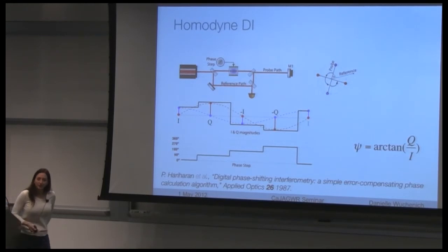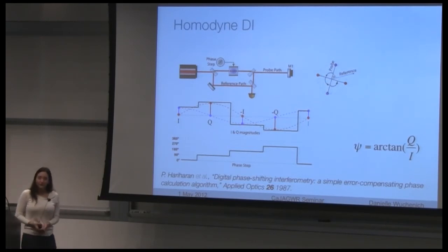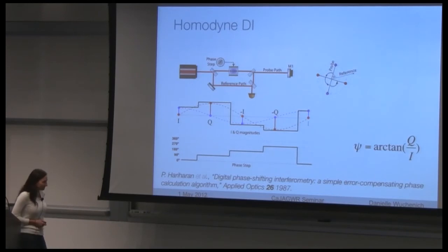So that's already what we had before. We can now use this phase modulator to do two things. Not only apply the pseudorandom noise code for signal isolation and multiplexing, but we also use this to jump us to different points, basically to sample the I and Q the same way that the heterodyne does, but we don't necessarily need it to be doing it all the time.